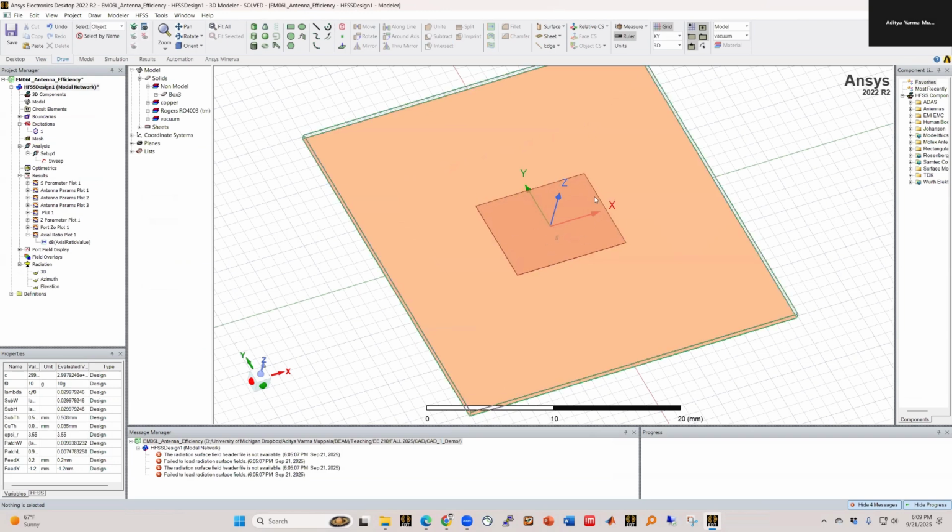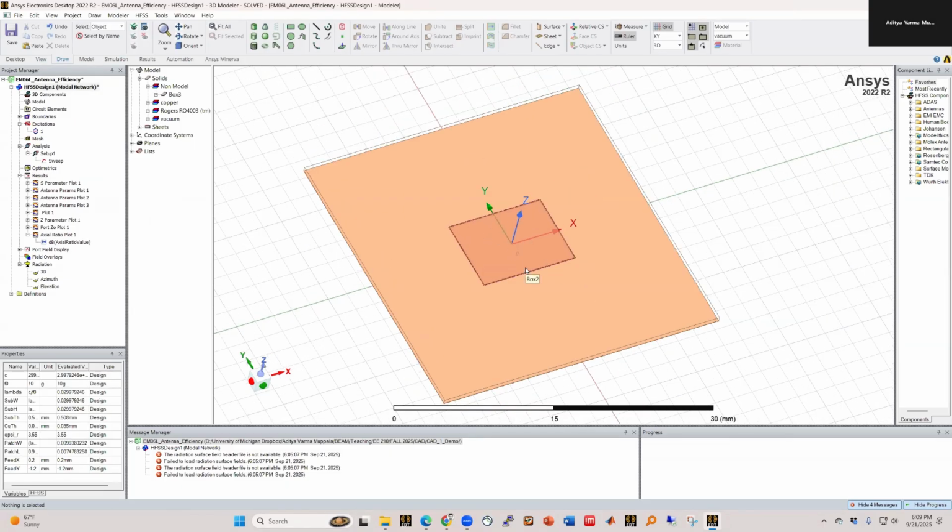So along this direction, we'll actually plot the currents today as well. And we'll see that the currents flow in this direction along y hat. If the current is along y hat, then in the far field, the electric field is also along y hat, right? Because the far field electric field is R hat cross J cross R hat. So we essentially get back J, one component of J at least, right?